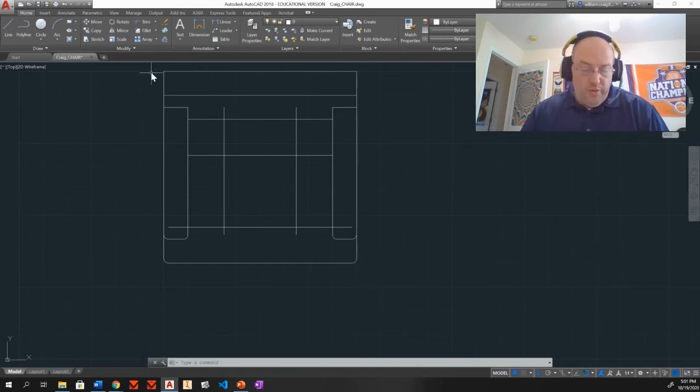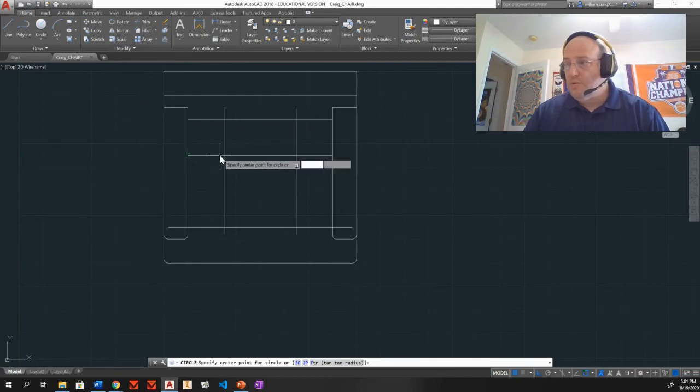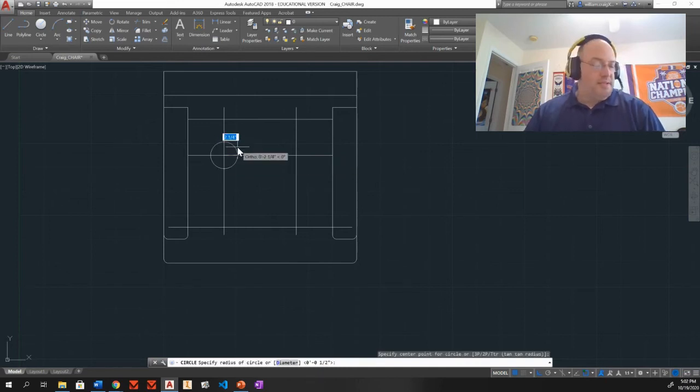So now we are at 7B, which we are going to do the circle command. I'm going to grab a circle. We're only going to draw one of these buttons. So I'm going to go right here in the center. You can see where the intersection is. I now have my crosshairs there, and then I have that green X. That's telling me I have an intersection. So that's where I want to click. I'll pull this out a little bit just so I start to make a circle.